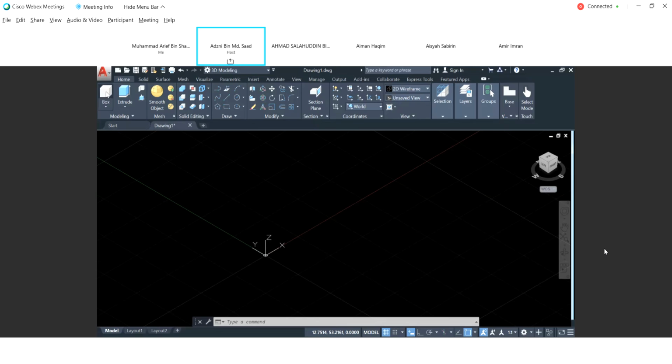When I click box here, as you can read in the command bar below, it asks you to specify first corner or center. Basically, the function is for you to construct the same thing as a geometrical object. But the box is basically a rectangle or square, right? So the function is the same as drawing using the rectangle function in the drawing ribbon.